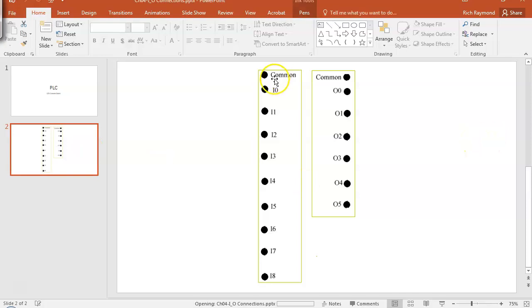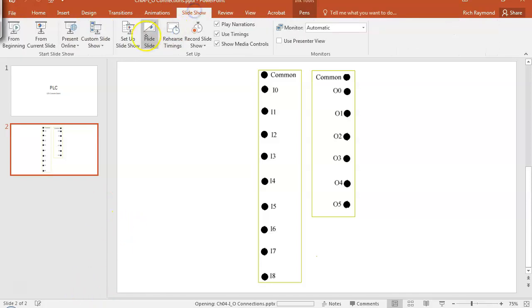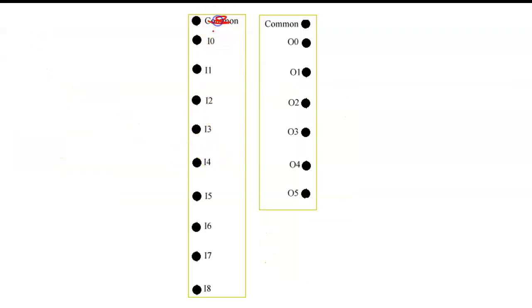I think the lab book's got 120 volts up here. First thing you're going to do is mark that out, because ours don't work that way. This is in your lab book, and you're going to change it over to what? Common, right? So this will be up here. If you look at your PLC, it says DC common. Then what do we have running up there? Well, we're running sinking input. So I've got the negative supply of the trainer running up here.